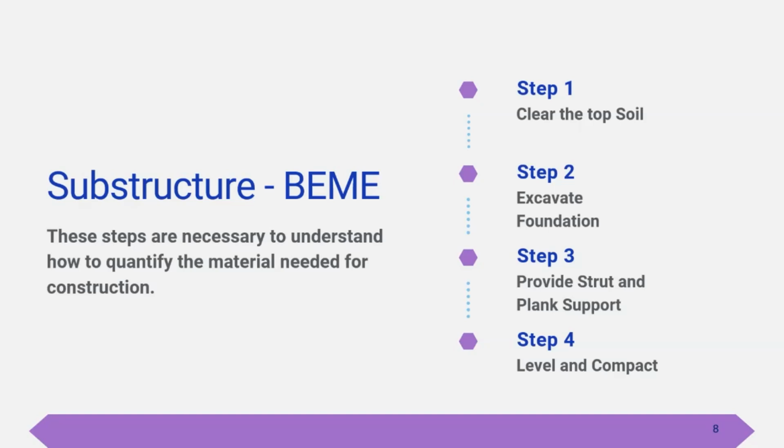So the first thing is that I clear my soil, then I go ahead to excavate the foundation. Why am I excavating the foundation? I'm basically excavating the foundation because I want to see the working area where I'll be placing my footing and whatnot. The next thing is that I provide strut and plank support. We don't use strut and plank support much here in Nigeria, probably because of how we were trained, or probably because of some bureaucracies. However, if you actually want to work properly on a site, it is appropriate that you put in place strut and plank. Why are you doing that?